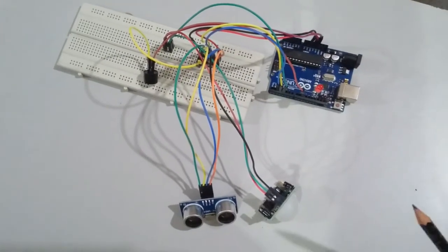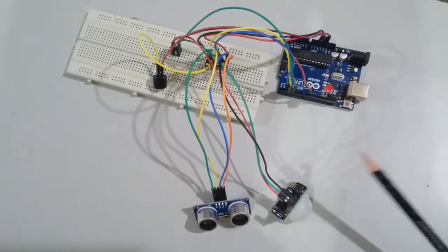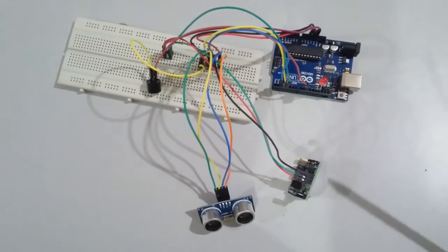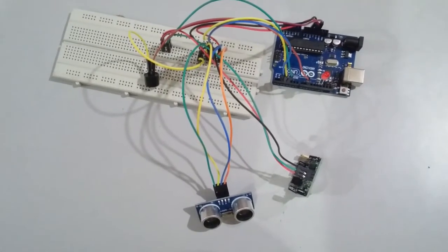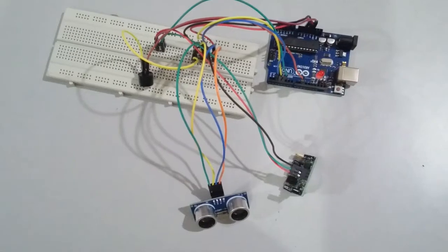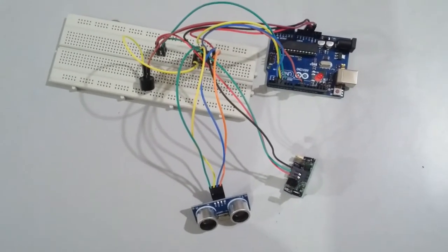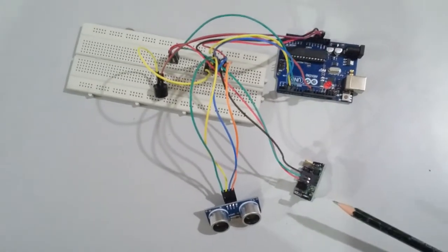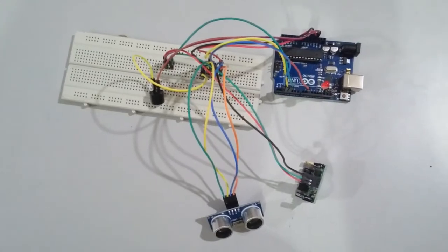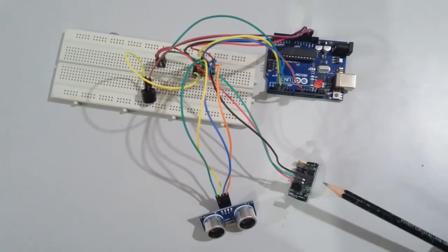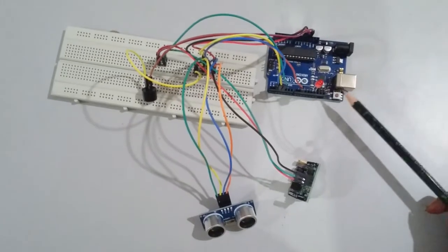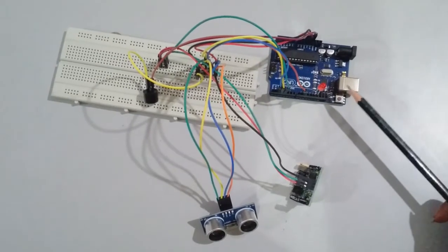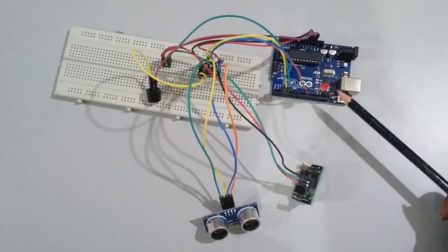The PIR sensor, that is passive infrared sensor, detects change in the infrared level of our surroundings. Unlike a normal infrared sensor, that is an active infrared sensor, which has an emitter and receiver, the PIR sensor only has a receiver node that will detect the infrared level emitted by the human body, and accordingly it will send output to the Arduino board, which will take actions accordingly based on the output it gets from the PIR sensor.